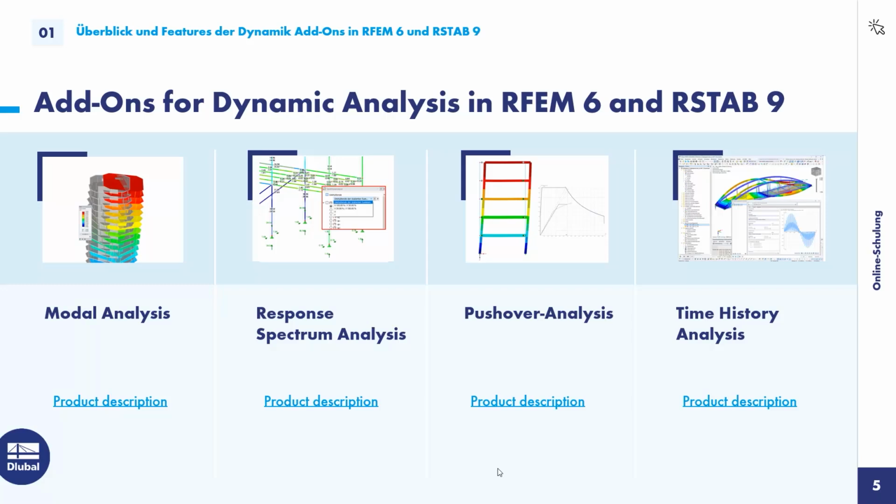The response spectrum analysis itself combines the response spectrum with the eigenfrequencies and creates a state of the system, let's say. It could be created by applying equivalent loads, or the equation can be solved directly to get the internal forces as well as the deformations. That's done currently within RFEM. You can just select the response spectrum and some important modes for it, or let's say 90% of the modal mass you would have to select. And with that, the rest should be automatic. That means you get an envelope of results for the modal combination and the directional combination. The final result is already automatically inserted in the seismic design situation, and that means it's just considered in the design.